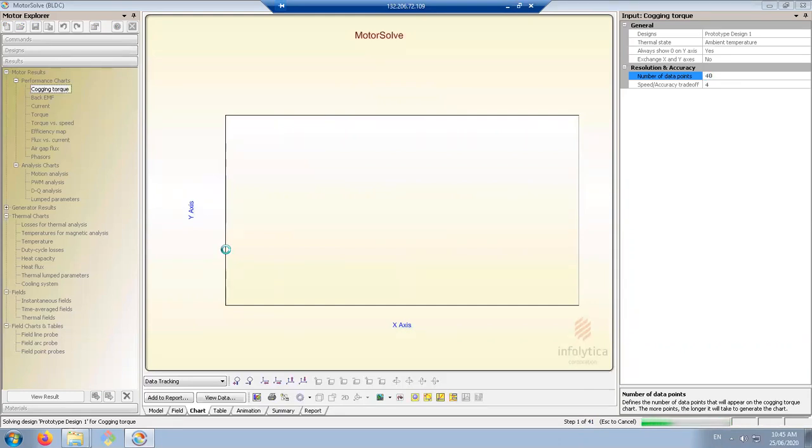This is the bottleneck of FEA-based solvers. They are slow, as you can observe here, right? That's why running an optimization routine where you need to run the finite element solver for several hundreds or thousands of samples will be really overwhelming and time consuming. So you should be patient, to be honest. Unless you have some HPC platform to run the finite element solvers, for example deploying the models on a cloud server and running them in parallel. That will be amazing.